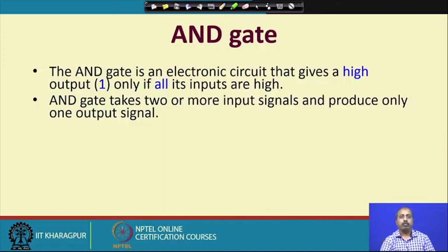So, that was the AND truth table, if you remember. In the truth table output column, it had 1 only when all the inputs were equal to 1. Any of the inputs being equal to 0, the output was equal to 0. Symbolically it is represented like this: one straight line and then two straight lines, in front of it there is an ellipse. So, this is the symbol. Whenever we are trying to represent one AND gate, we will be using this symbol. So, this is a 2 input AND gate. There are 2 inputs A and B and one output which is marked as AB here.